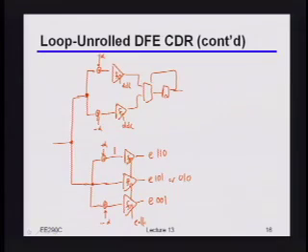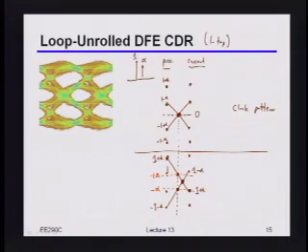But to do it live, I think has similar problems as what the normal loop unrolled DFE has, in the sense that there's really no analog level that you're looking for that gives you exactly that information. To be fair, the only saving grace here is that you really could look for this point in time here, but that would assume that you locked in the right place in the first place. Right? So I'm not exactly sure how you would check that you're really in the same time when you're doing the estimates this way versus that way.